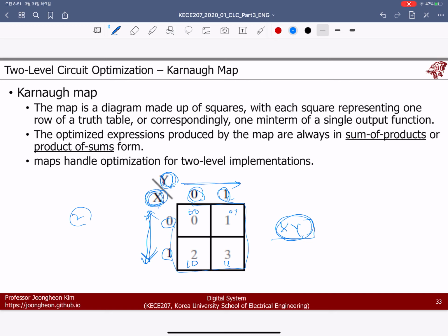Okay, so here this is a min term because this is talking about 0, 0. Then it means that this is x prime, y prime, or x bar and y bar. So in min term, x should be 0, y should be 0, because x should be converted to 1 by this complement, and y 0 should be 1 by this complement. That's why eventually we have 1 product 1, so we have 1 as a result. So this is the min term what we studied before. That's why here we can say that this is x prime, y prime in terms of min term definition.